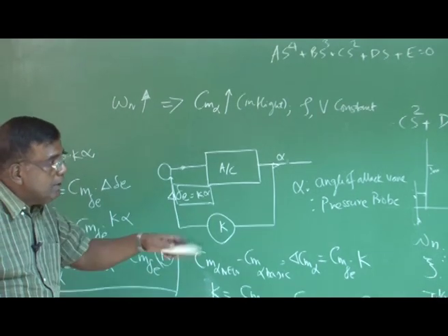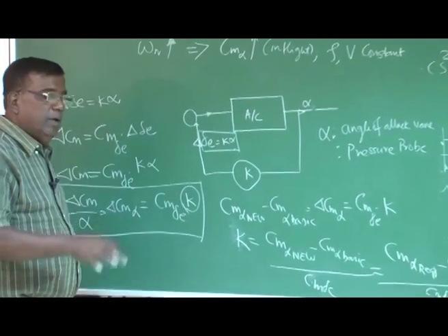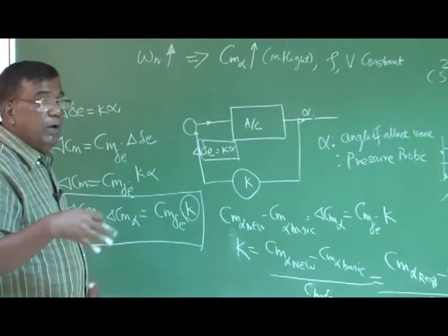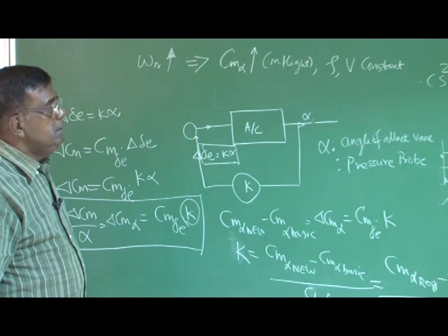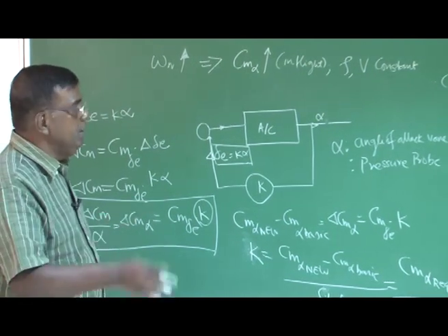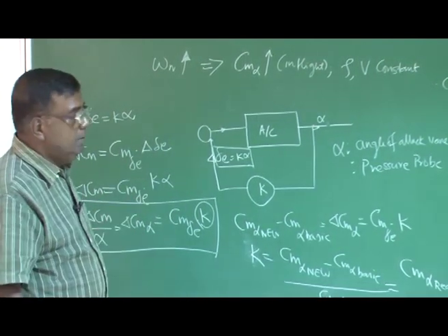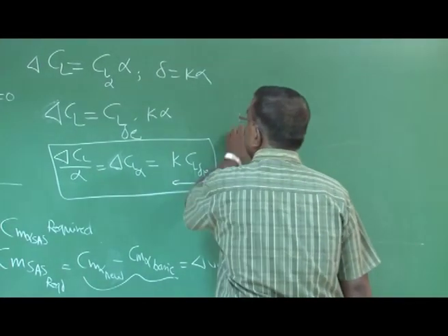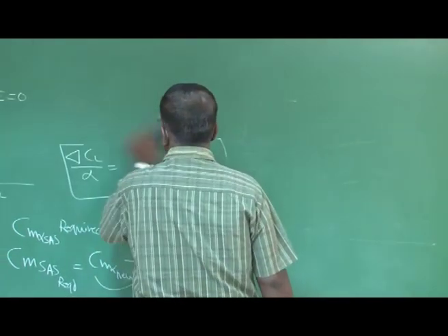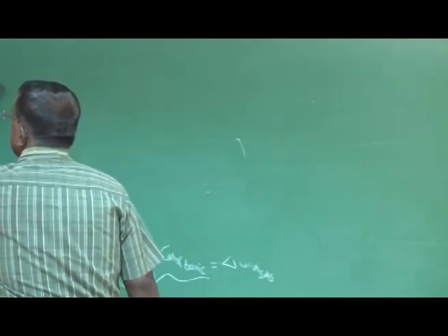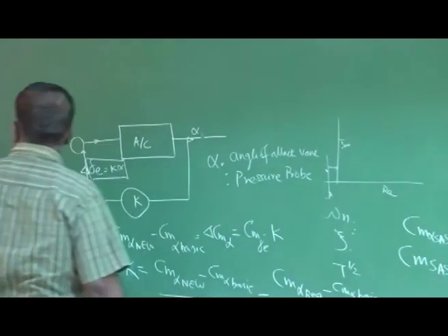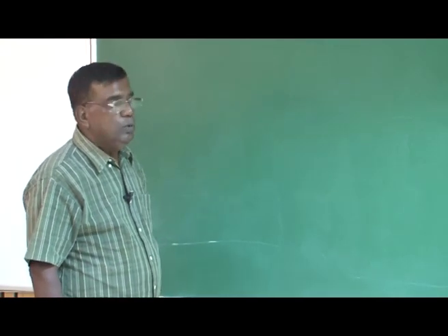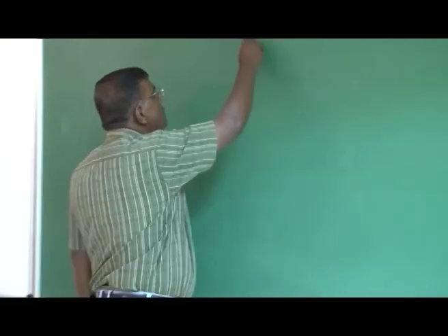Okay, because we have started with the very first approximation, we have taken the pure pitch case, and that is the way to start, because otherwise it becomes very complicated. So this sort of iteration goes on, right? Now if you want to look at how to change the damping ratio, let us also see. Once you have understood this, how to change the damping ratio should also become very simple for you. Let us not forget, we are talking about the longitudinal case.